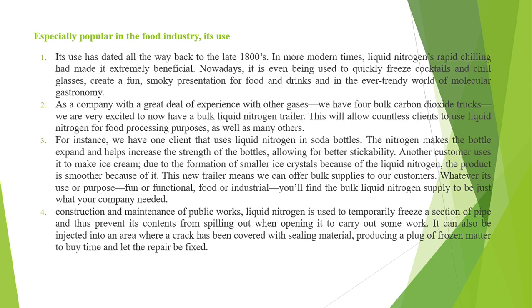Construction and maintenance of public works. Liquid nitrogen is used to temporarily freeze a section of pipe and thus prevent its contents from spilling out when opening it to carry out some work. It can also be injected into an area where a crack has been covered with sealing material, producing a plug of frozen matter to buy time and let the repair be fixed.